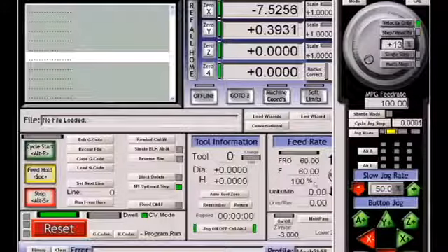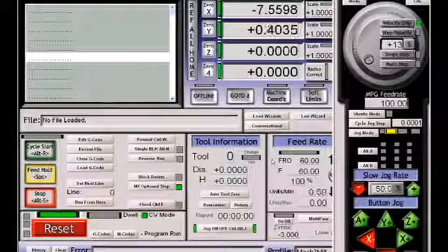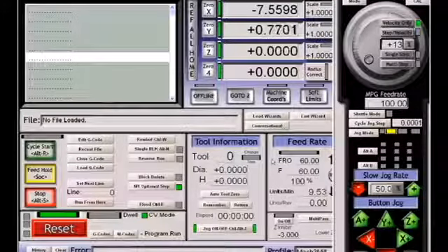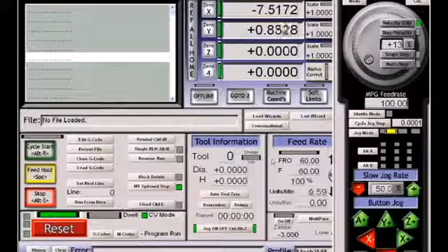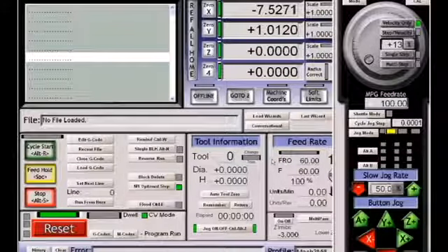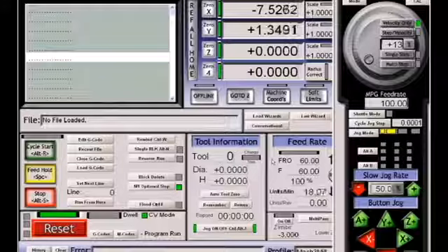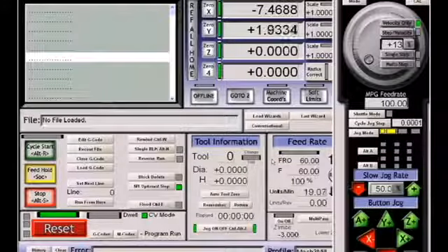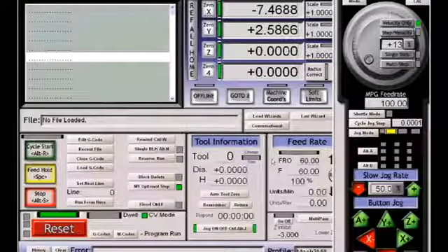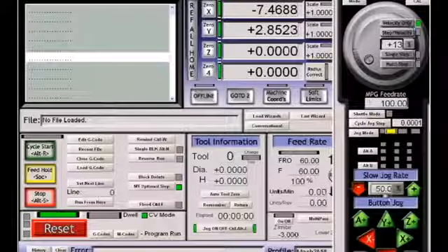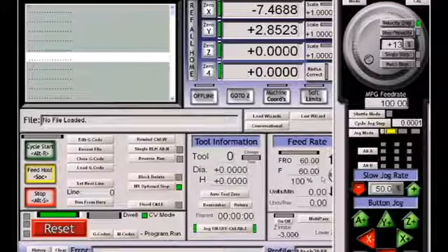And what that does is give you 2 speeds of jog. Just hitting the arrow keys on your keyboard, you can see I've got a speed of approximately 10 millimeters per second being fed. If I press the Shift key at the same time, I now go to fast jog, and I have 20, which is twice the slow jog. In other words, slow jog is 50% of the maximum rate, and you get the maximum rate by pressing Shift. Notice when I press the Shift key that the fast jog indicator lights up. Otherwise, you're on normal speed.